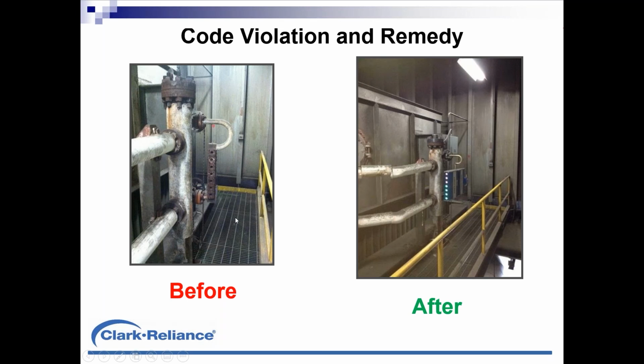We'll look at an example now. Here's a ported gauge, similar to what I'd mentioned earlier, with no lighting fixture on it. I took this photo myself. You can see there's no easy way to see the level, and someone might try to shine a flashlight on the back side, look in the front side, but keep in mind, if this gauge is operating at 1,500 pounds steam, that chamber is sitting there at about 600 degrees Fahrenheit or close to it. So I wouldn't want to get too close to it and slip and bump your arm to it, whether you're wearing gloves or not.